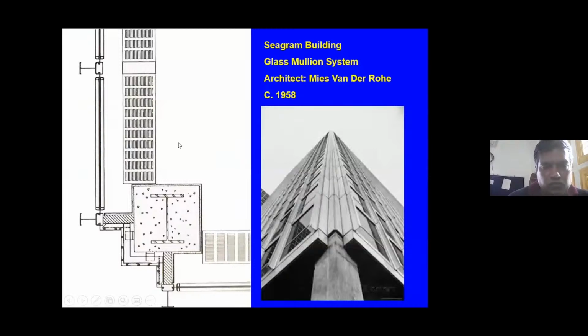And the detailing would work like this. Of course, the whole interesting part is these mullions. They per se are not structural, in the sense they are not taking structural load. They are only taking the glazing load. So this is the stick system.